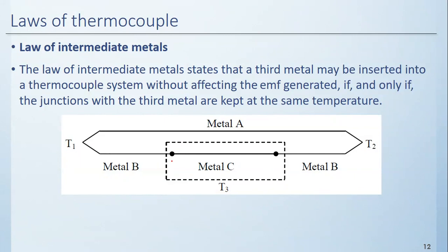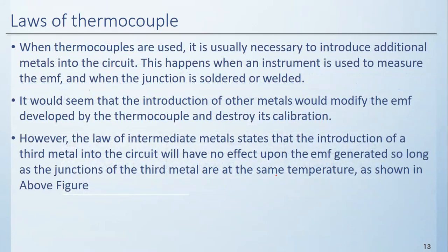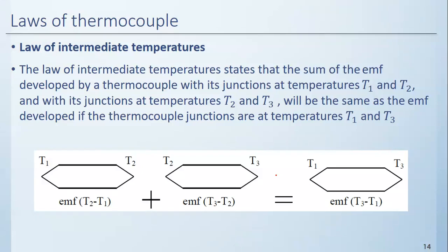See here, you have the temperature T3 here, and here also you have the temperature T3. So the two ends of the added metal are at the same temperature. That means the EMF produced is unaffected by the addition of the third material. So here is the statement.